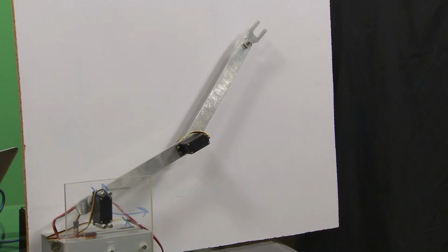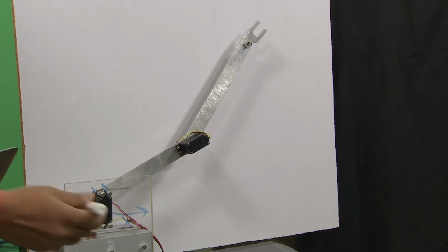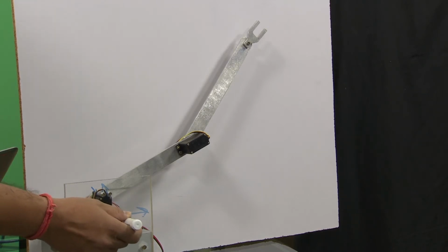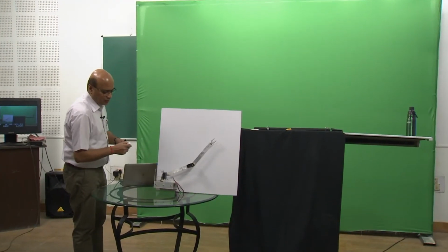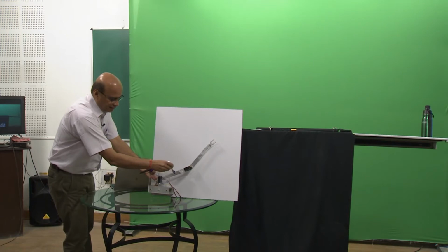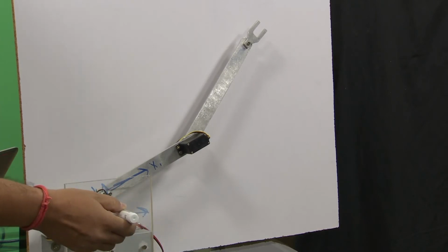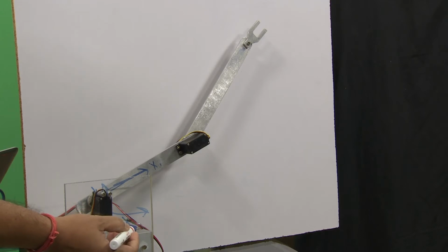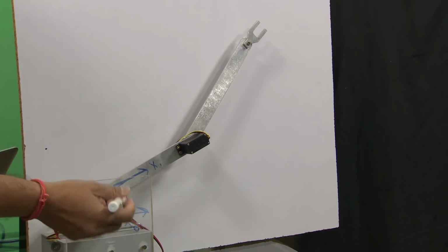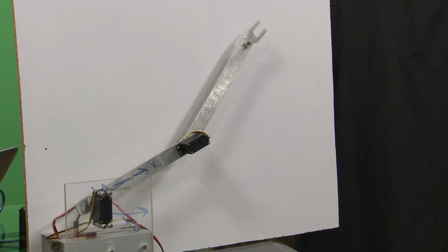If you look at the frames, let us go back to this again, we have two frames here. One frame is my 0 axis which is assigned to the base frame. So this is my 0 which does not move. Now I assign the first frame to the first link. So this is my first link, and if you can see through here, that is my first axis, my x1 here, and the z1 is also aligned with the z0 and it is the same axis. Now when the link moves, the angle between this x0 and this x1 will change, and that is what I call my theta1.